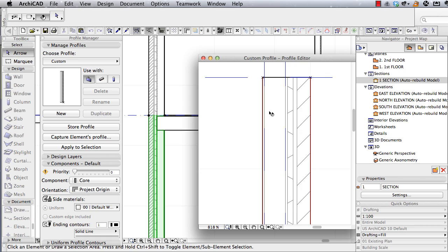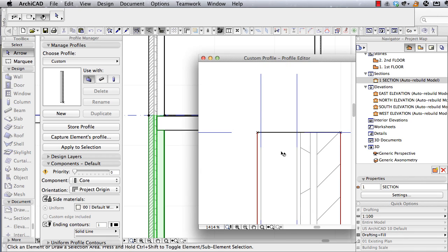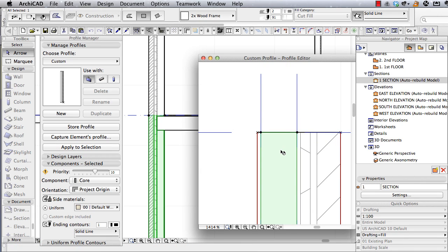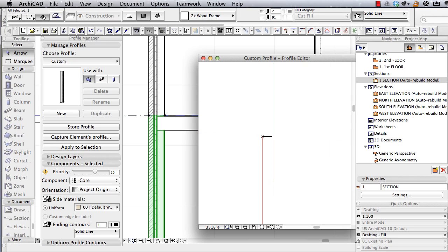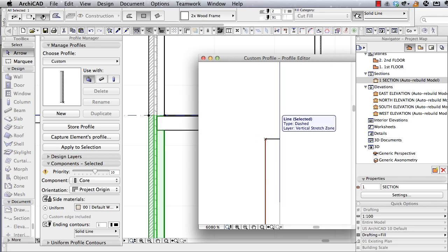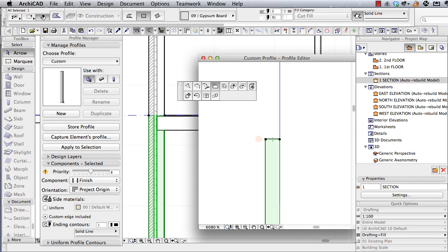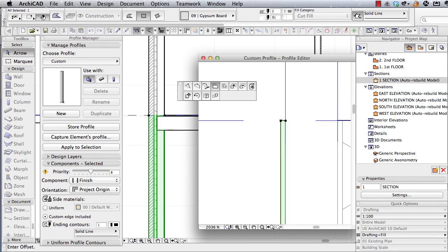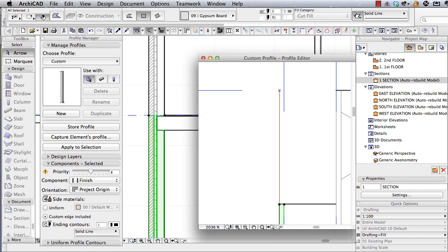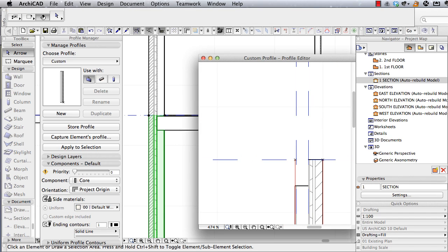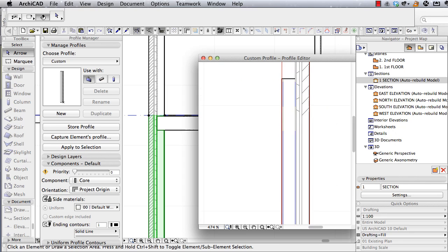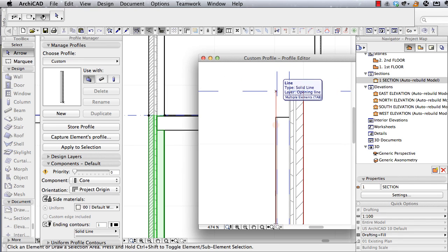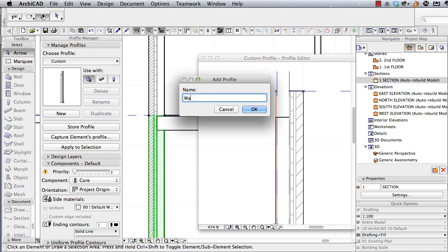And what I want to do is actually bring this fill that represents the framing area down, using the pet palette, just the standard controls, a certain amount. And then I'm going to do the same thing with this fill, and snap it into position here. So now this wall is actually notched for where the slab would fit in. I'll store this as wall type 1.